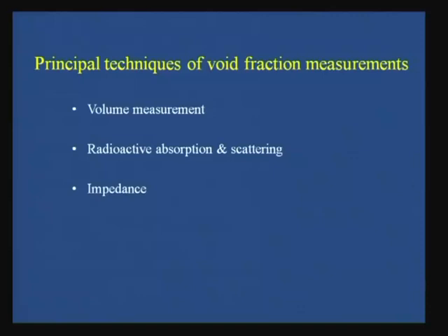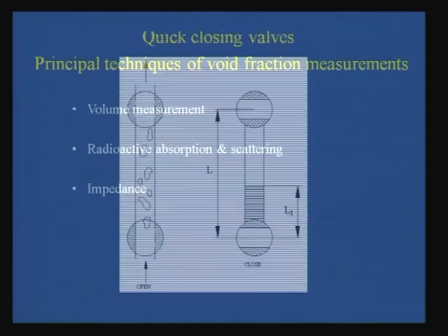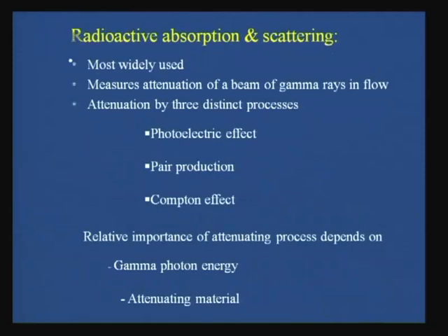And then the other technique which is very commonly used is the impedance technique, because very frequently we find that the electrical conductivity of the two phases is different, or the electrical capacitance of the two phases is different.